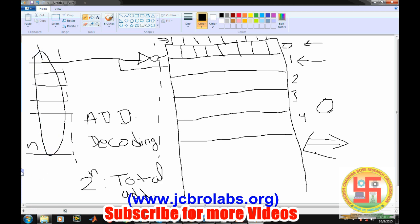8051 has a 16-bit address bus. As we just discussed, the 8051 microcontroller has an 8-bit data bus, because it is an 8-bit microcontroller, and it has a 16-bit address bus. So you can understand how many total addresses, 2 to the power 16, and it comes out to be 64 kilobytes of data that can be accessed from the 8051 microcontroller in one go.